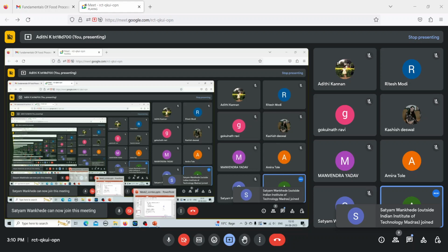The Burger model, which is a series combination of the Kelvin and Maxwell models, in which the total strains are summed up. The strain is equal to the summation of the first term, second term and third term, which I will explain right now, where lambda retardation is the retardation time for the Kelvin part of the model. Let's look at the first term, that is sigma naught by E naught. This term is for the spring that is outside the parallel, the spring of the Maxwell part of the model. The spring outside the parallel system is what is described by this first term.